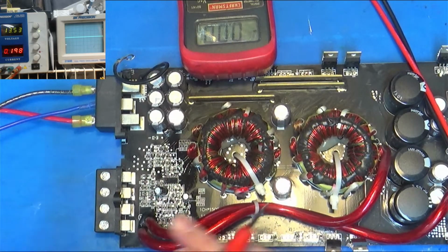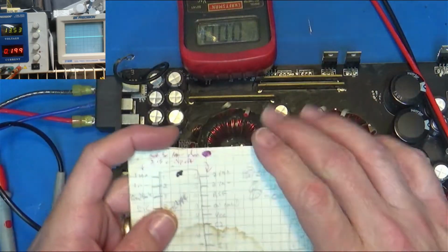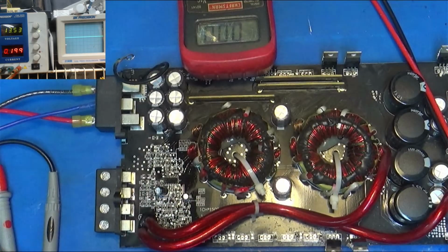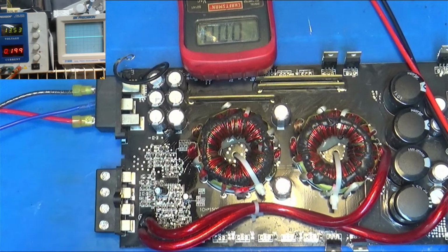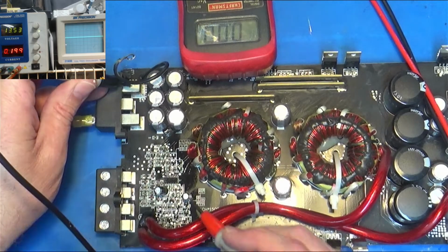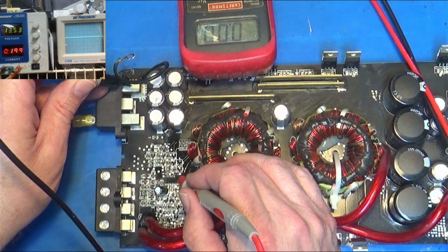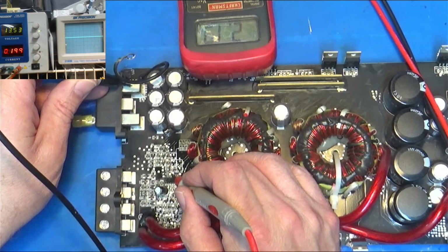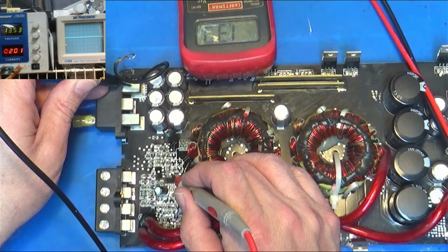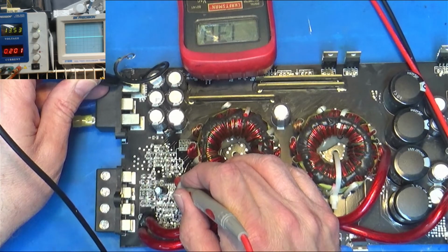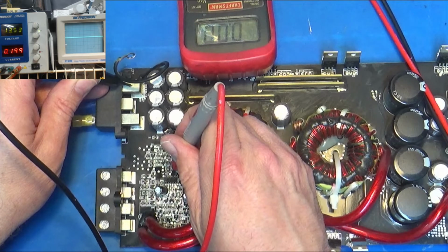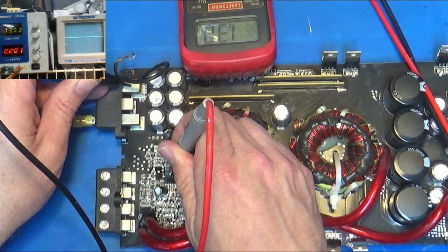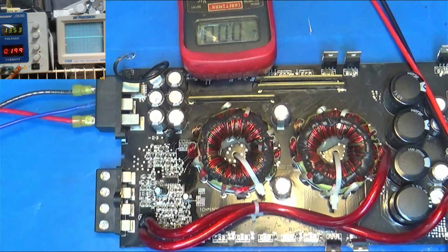So we weren't getting any power. If you remember in the live stream, I had my little cheat sheet card here, and it says VCC is pin 12. So we put our black probe on ground. So it's 9, 10, 11, 12. Our meter's showing maybe 2 volts here, and we're not getting anything. Still not getting anything. Should be getting 12 volts and we're not. So I think it's taking that chip out.